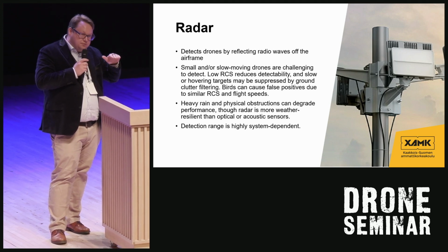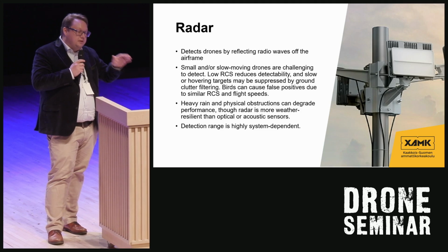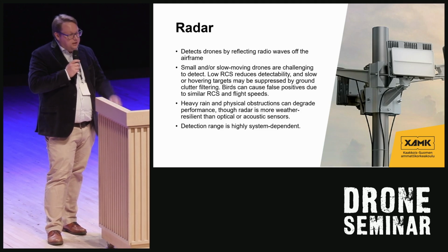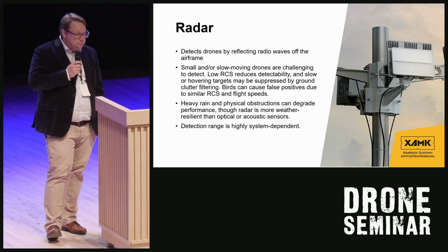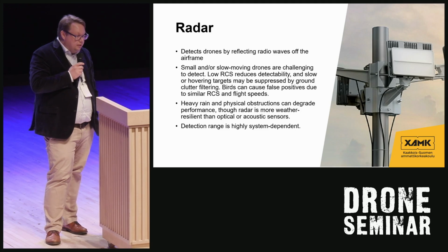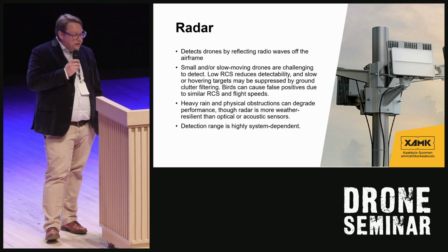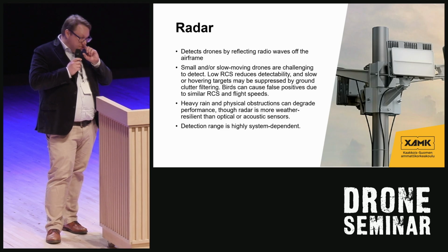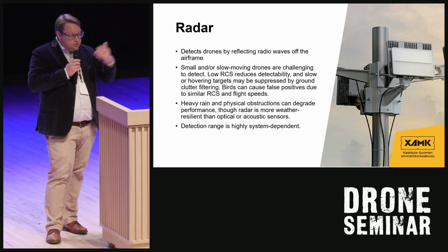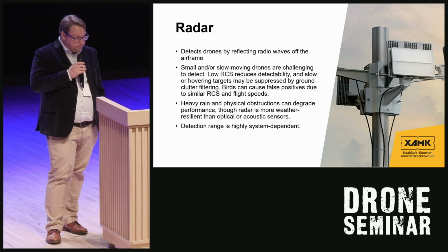If the drone is flying very low, it might be very difficult to separate the drone echo from the ground clutter. Also, heavy rain will affect how effective the radar is, because the water in the air will also reflect back some echoes.